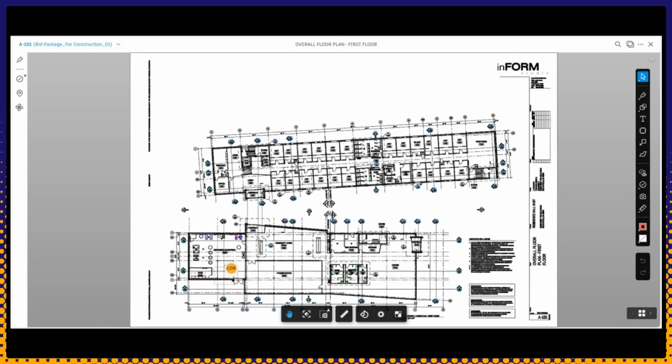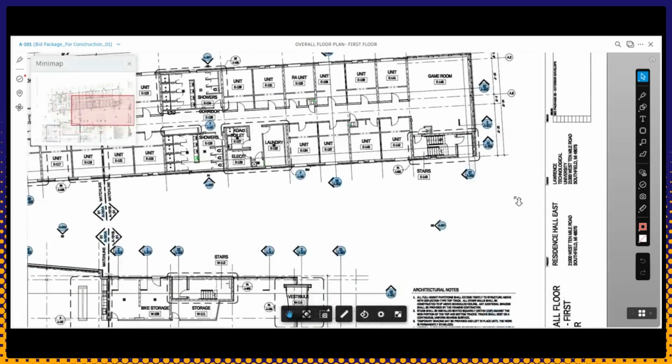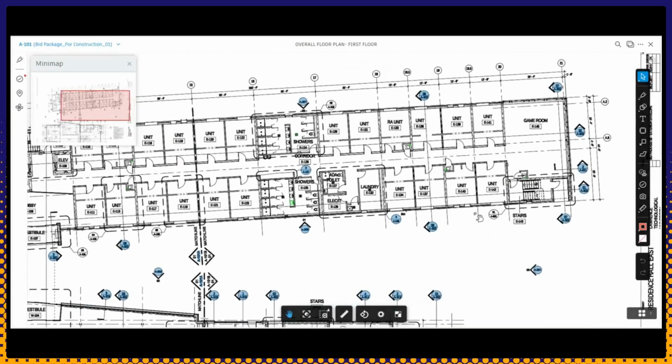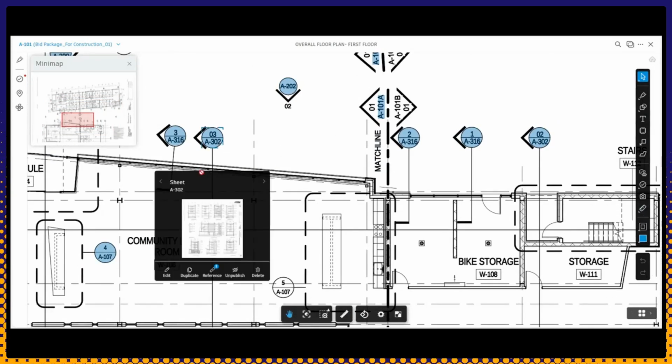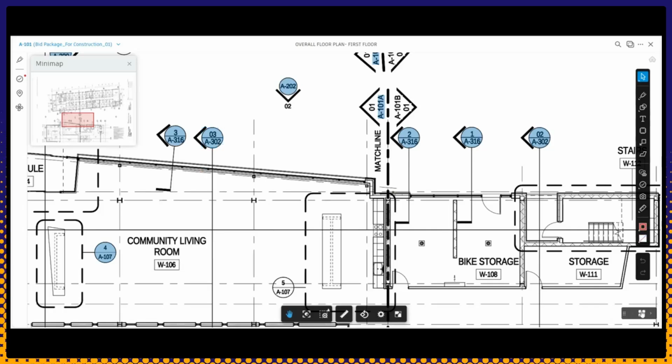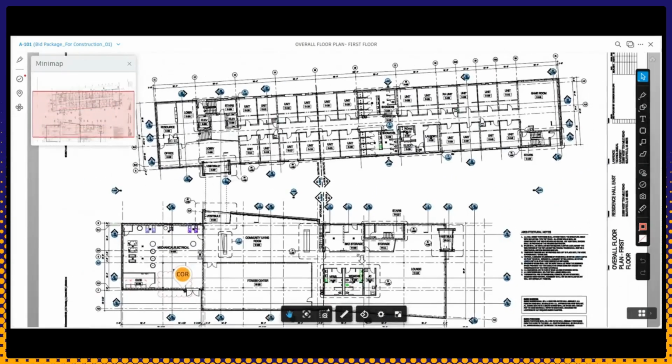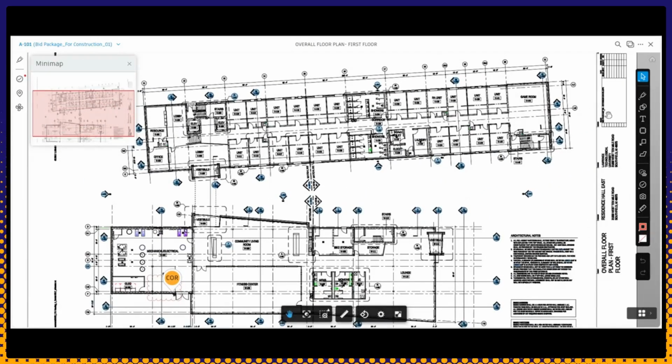Whether you're in the office or in the field, you can always access your drawings with this integrated viewer. Autodesk Build is available for iOS and Android tablets, so you can easily view sheets and drawings from the field. With this tool, you can scroll, zoom, take measurements, and easily switch between a floor plan and a specific section or between different sheets. What is interesting with this viewer tool is that you can easily mark up your sheets,